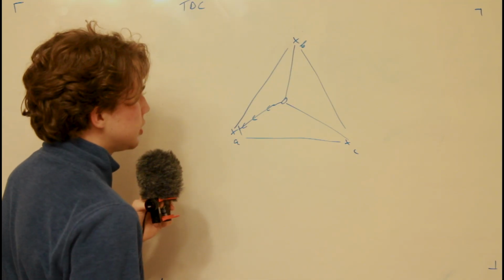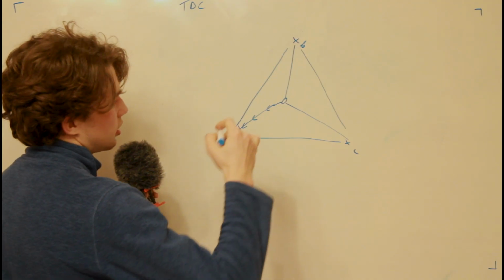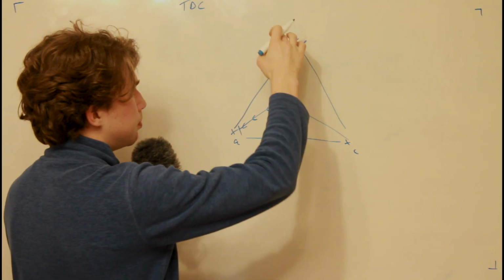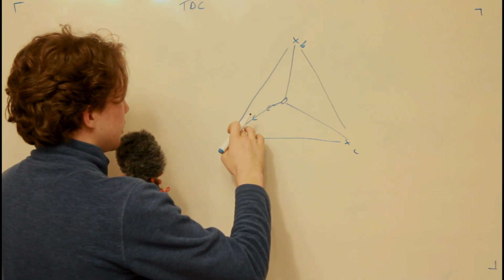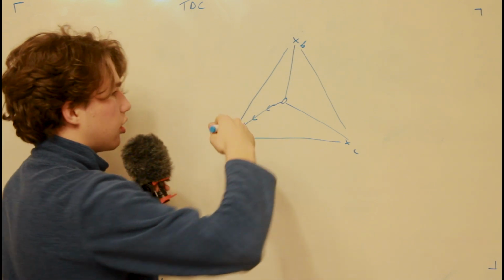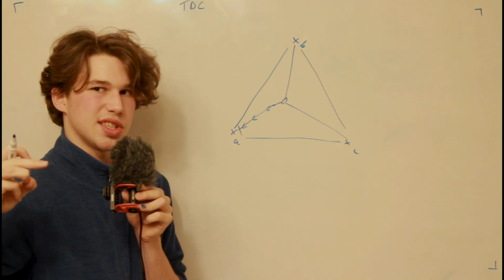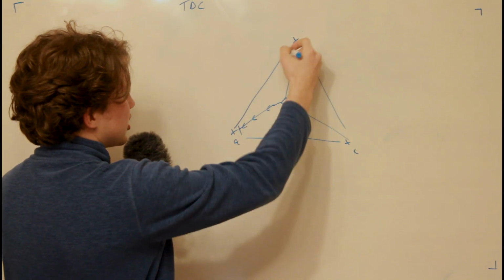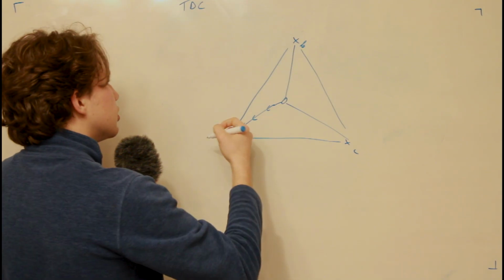When we have all these values, we can construct this triangle. So what Floaty does now is the same process, but the lead motor is motor B. The AS5600, that's the name of the magnetic encoder, starts reading. And after it stopped reading, we can just convert these angles it collected to centimeters.